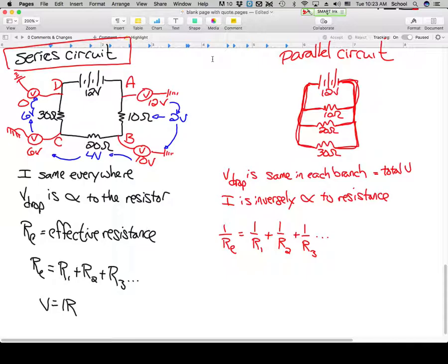We're gonna get triple parallel circuits. Okay, so first we're going to find out what our effective resistance is. To plug this in and make the algebra super simple, we just cheat on our calculator, and we look for a button on our calculator that says x to the minus 1. It is located right above where it says squared. Everybody see it? That's cheating. The x to the minus 1 button takes the number that you put in there and it flips it, inverses it, just like it says here.